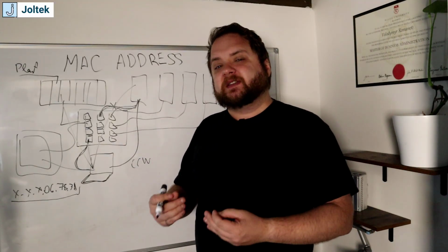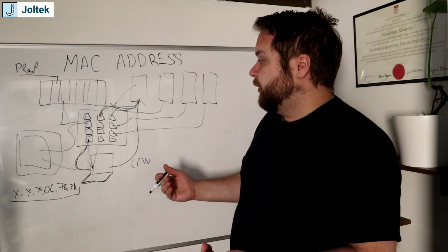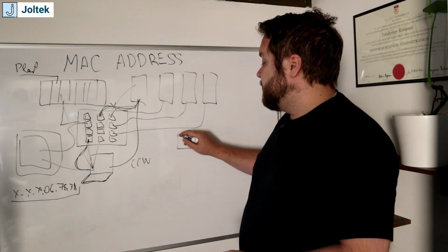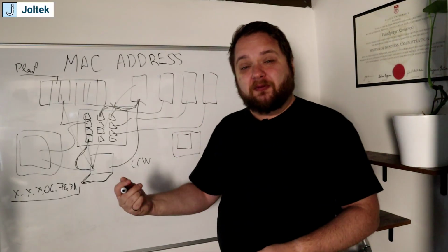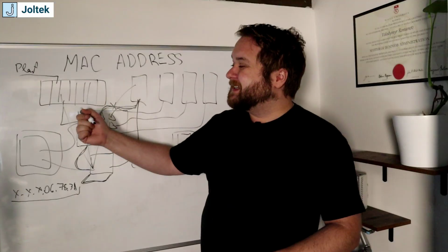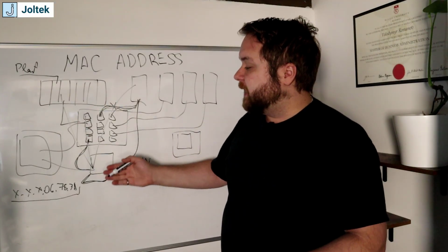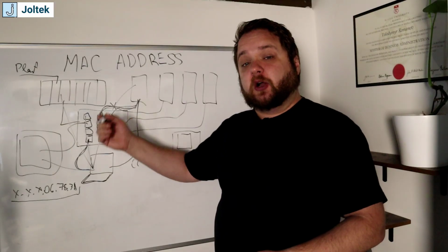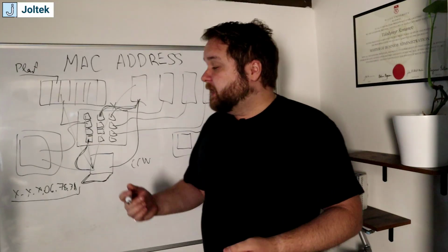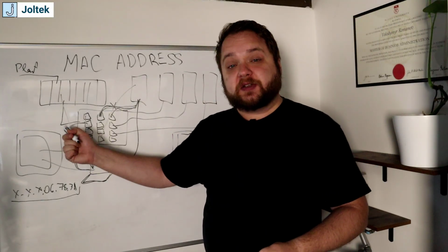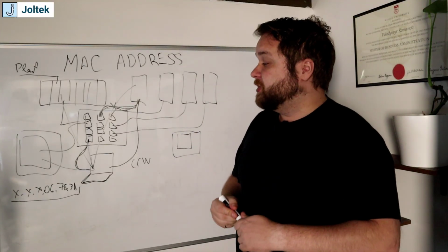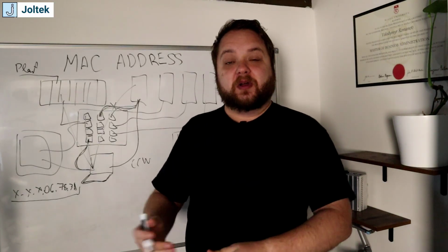What happens once the system is already running, and for example, let's say you have a request, we need to add an extra HMI, right? You can commission that HMI before you put it onto the switch or onto the network. But if you want to make changes to an existing set of equipment, let's say you walk up with your laptop and you plug in, and you now see a lot of different devices on that network that you're not necessarily familiar with, it is very easy to make the mistake and connect to a different device. And in the worst case scenarios, and I've seen this happen, you would have engineers that will basically overwrite the program of a PLC.